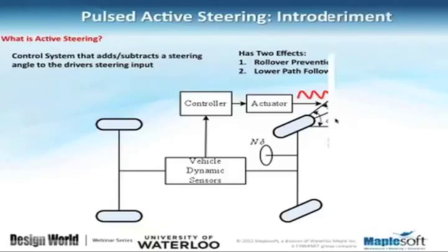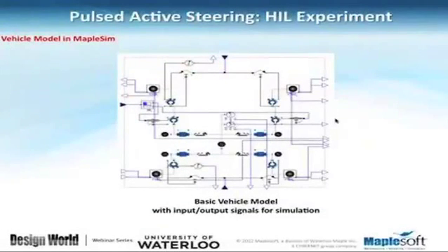So what we did, we used again MapleSim and all the standard components that we have in MapleSim in order to come up with the overall model of the vehicle. I'm going through this a little bit to see how the vehicle model is established here. The center part that you see here is the mass of the vehicle, and these four are the corners of the vehicle, and those are the suspension.